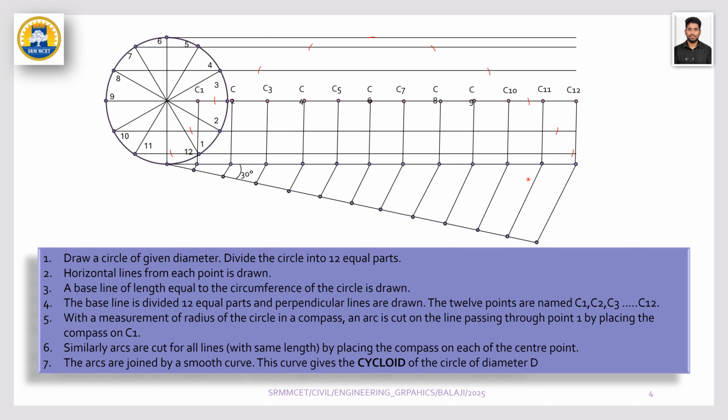On the whole, we have to draw a line starting from this base point, passing through all the arcs. It should be a smooth curve. Take your pencil and draw a smooth curve such that it doesn't have any breakage. We'll obtain a curve just like this, and darken this curve, as this is the final curve that is to be obtained.